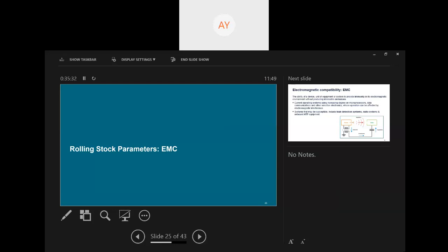because we know that on the track we have track circuits, AFTCs, sensors, wheel sensors. They all work on a given voltage and current level in a defined frequency band. And if the rolling stock can emit or conduct that kind of energy into the rails, that can become an issue with the train detection systems. So that's why EMC is a very complex requirement, and it becomes more complex when you look at the variety of trains and variety of train detection systems available across the world.